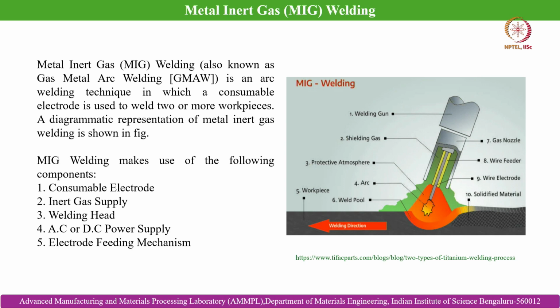Here we are dealing with a consumable electrode, and there is also a gas shield kept over the joint to prevent oxidation and gas absorption. If it is a light metal, there is a high chance of hydrogen absorption in the joint, which can cause big porosity, and can then weaken the structural integrity of the joint and cause failure while in service.